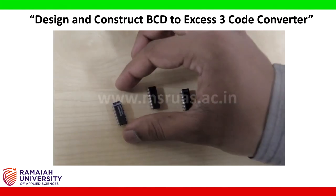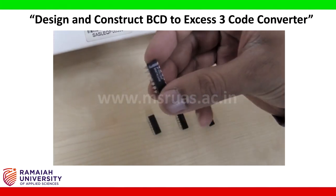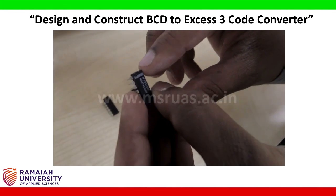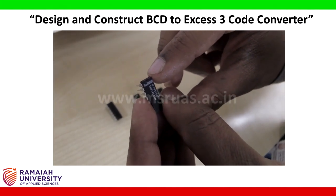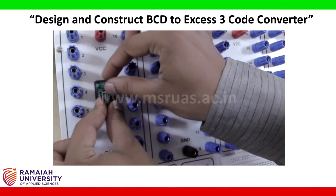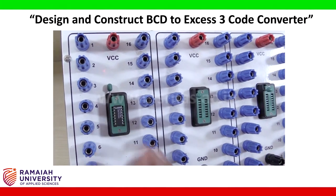Now we will place the ICs into the IC base. First I am taking NOT gate 7404, and before placing the IC into the IC base, make sure the IC has a notch that should always be in the upward direction. So I am taking it and placing it into the first IC base. After placing it, close the lever, make sure the IC is not coming out.